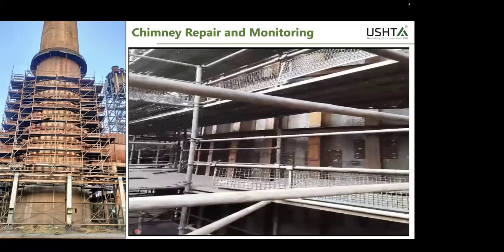So you can see here the base plate is somewhere else, here it's somewhere else. Even the holes in the base plate are. So what we did was initially we drilled holes, then we took a template, and then the entire steel structure was made according to that.